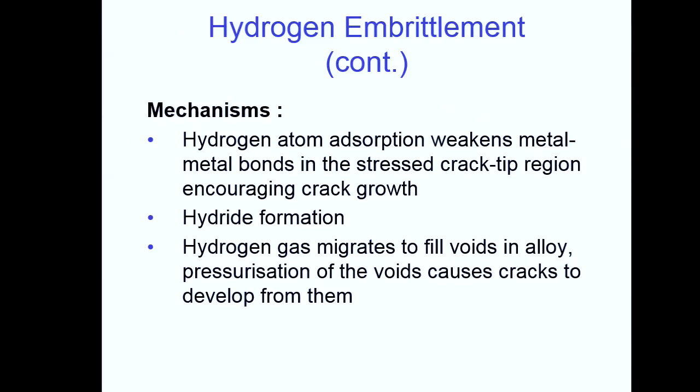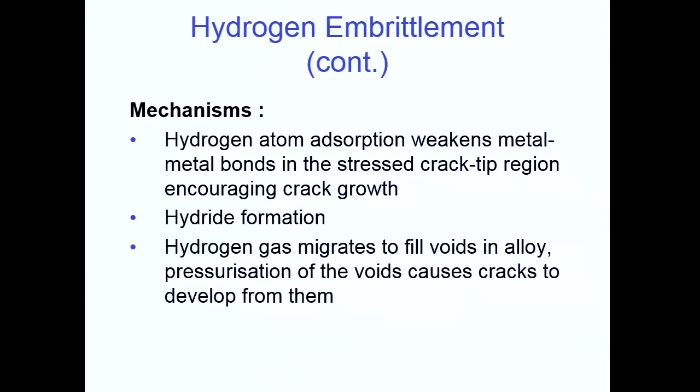So this one's less interesting for you, but it definitely occurs. And I'll show you an image if it'll behave itself. Yeah, not too bad. So this image here is actually a zirconium sample. And these little black features here are small intergranular cracks associated with hydride formation.